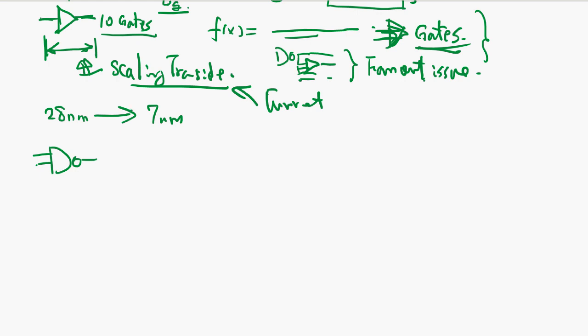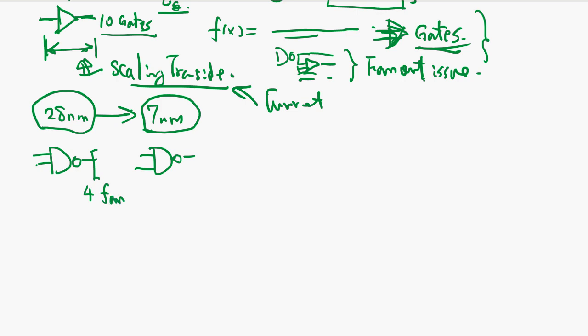When you move to a smaller transistor, obviously the gate current is much smaller, and we say, we used to drive a fanout of 4, and when you shrink the transistor, the other transistors are small too, so we still go for a fanout of 4.